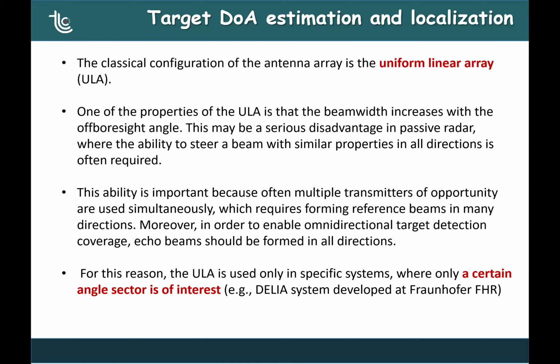Unfortunately, we know that when we use the uniform linear array, the resolution in angle is quite good when we are close to the boresight, say in a field of view that is minus 60 degrees to plus 60 degrees.